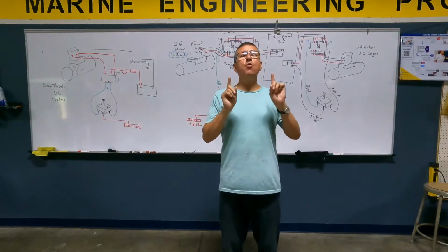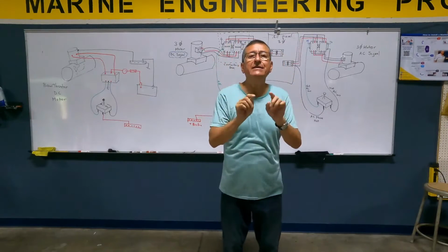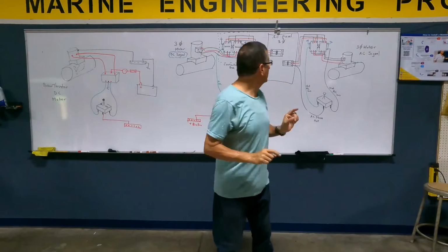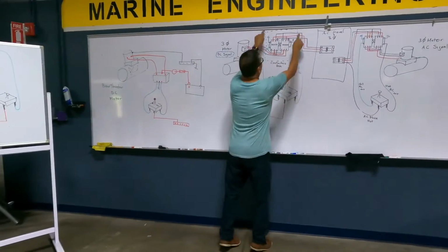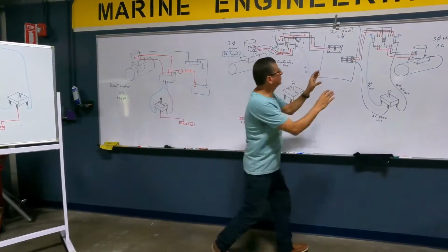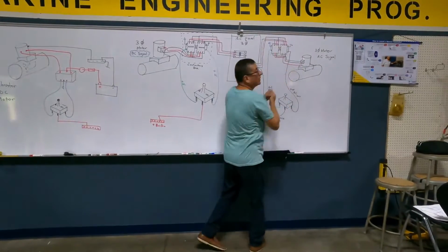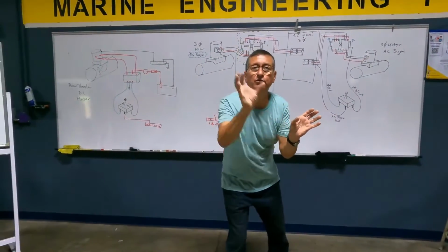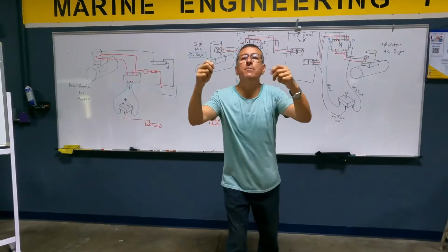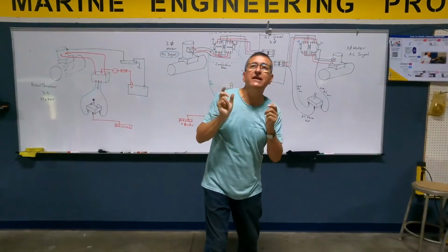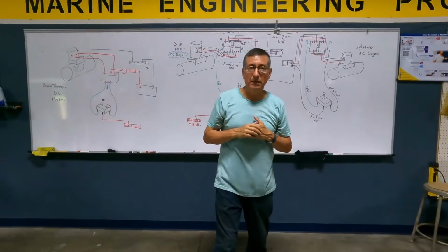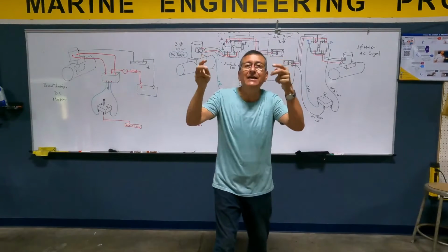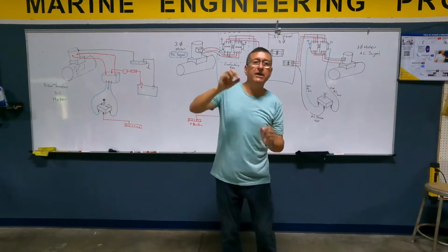Okay, verify where the contactor control box is, that box where the contactors are located. This one. Where is that box located? It's here, pretty close to the motor of the bow thruster. Let me open the box and verify if the signal is AC or DC. The signal is AC. Let me check.